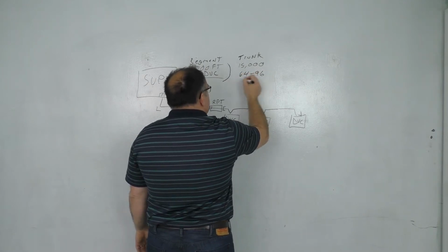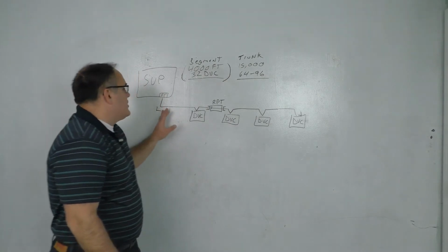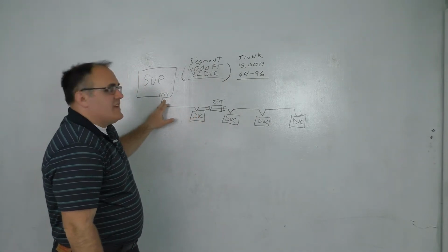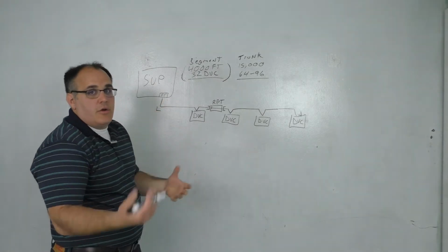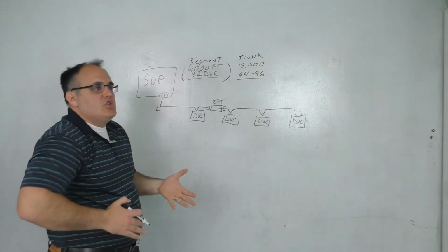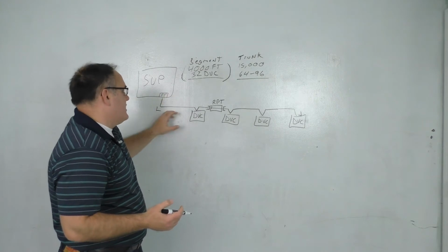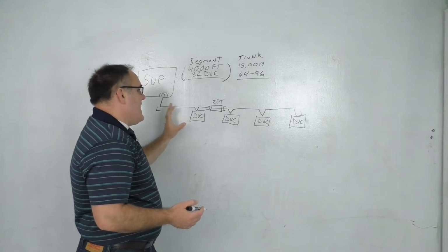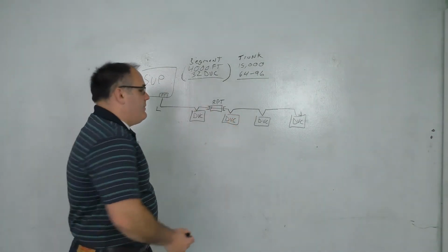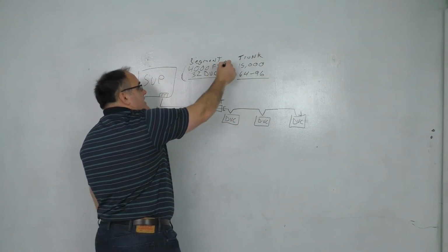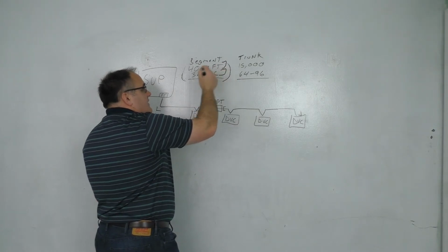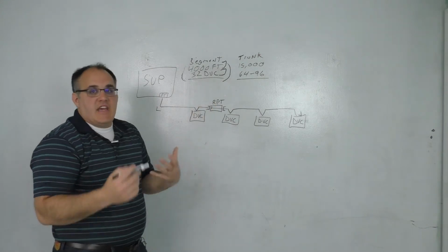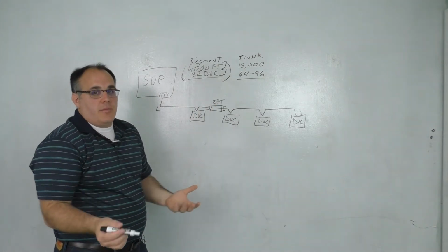64 to 96 devices. What's going on with these devices is that there's an electrical signal across 2 conductors, typically like an 18-2 wire. So you've got 2 conductors, and it's going from controller to controller to controller. And that signal starts to degrade over time. That's why we have repeaters, and that's why we have these device and length limitations. It's when you break these limitations that you tend to see degraded performance.